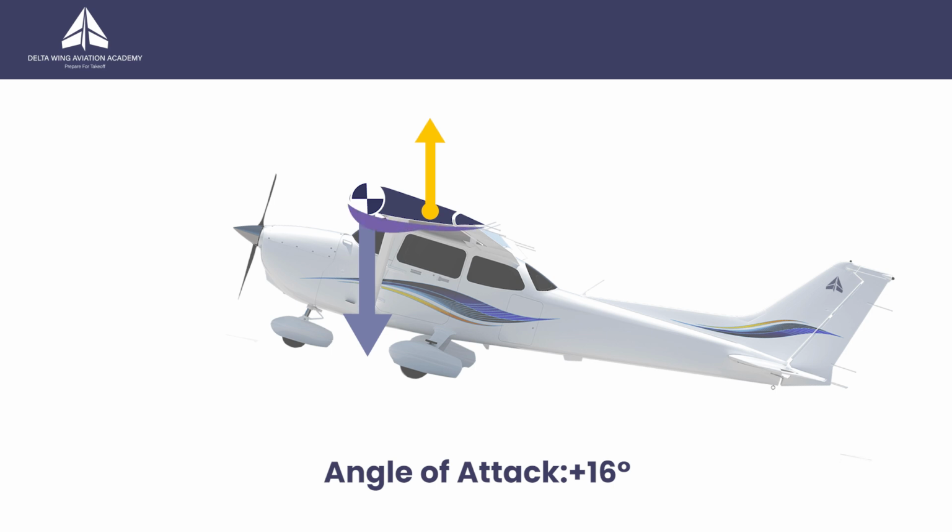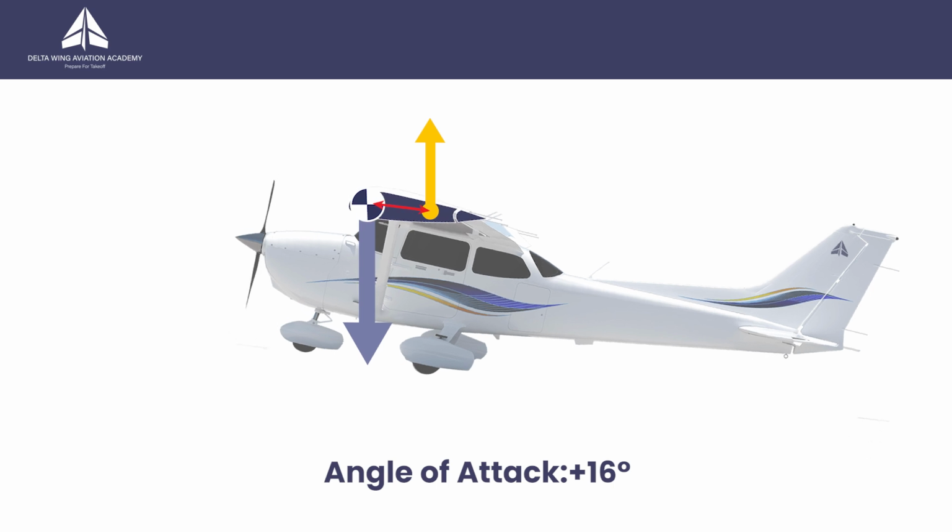Furthermore, a higher air pressure system below the wings has an increased pushing force near the trailing edge, which contributes to the rapid shift of the lift force vector towards the rear. This shift aids in recovery from the stall due to the increased moment provided by the lift and weight couple, resulting in the nose pitching down.